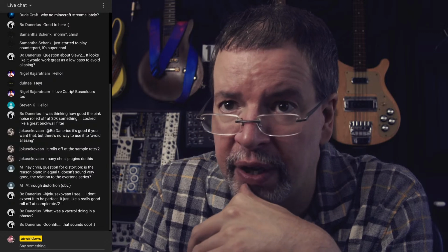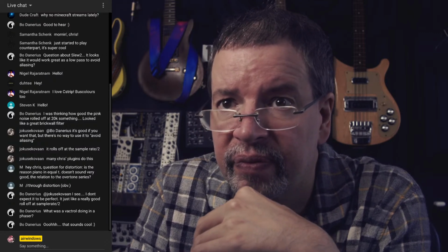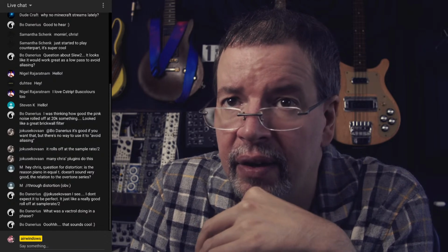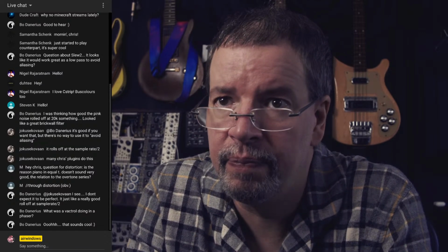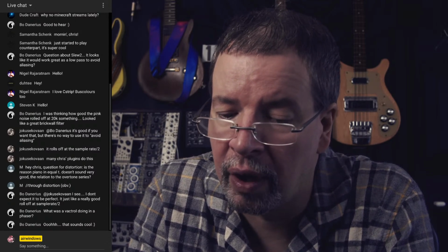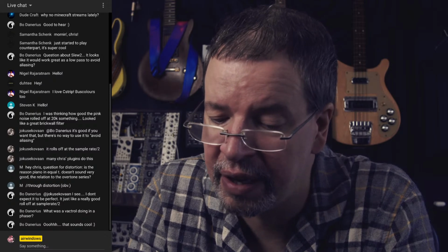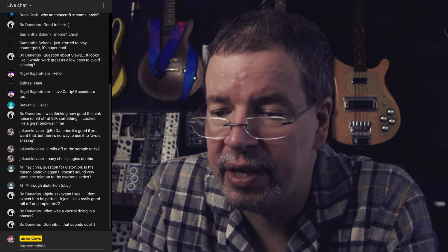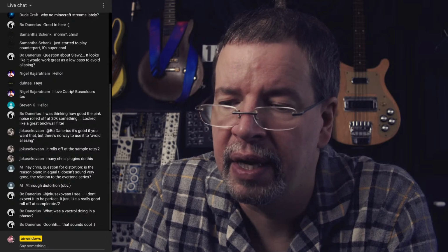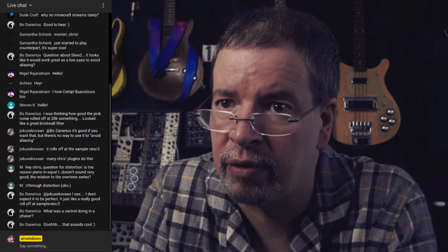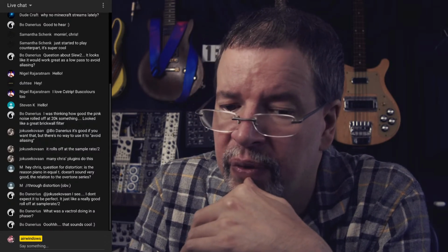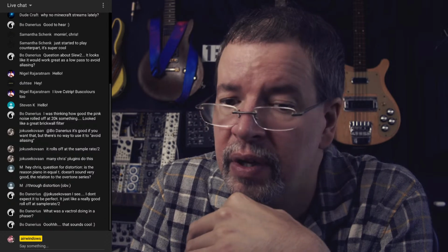So many questions, but yeah, that's the thing, Bo, using Slew2, you do get a really nifty little roll-off, which was quite accidental. I never designed it that way. But that is at literally the Nyquist frequency, and you needed to have it be at half the Nyquist frequency to do aliasing prevention stuff, or a third of the Nyquist frequency, rather.